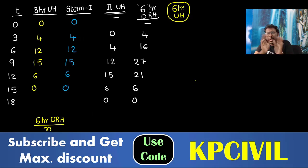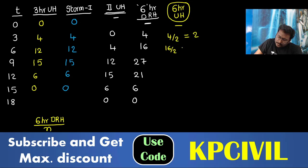Or simply, you are adding how many values? You are adding the storm 1 value and the storm 2 value, so you can divide by 2. Divided by 2: 4 by 2 is 2 meter cube per second. 16 by 2, 8 meter cube per second. 27 by 2, 13.5 meter cube per second. 21 by 2, 10.5 meter cube per second. 6 by 2, 3 meter cube per second.